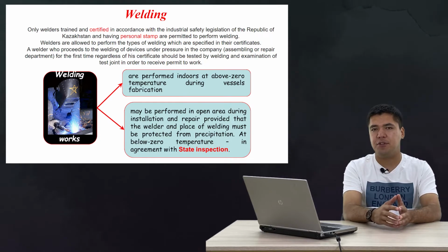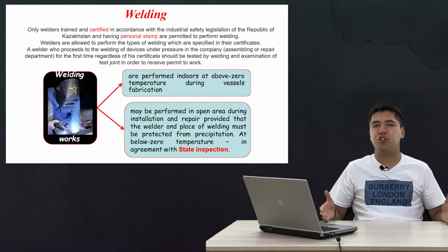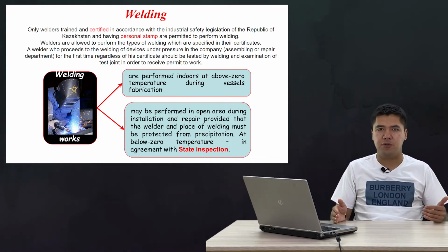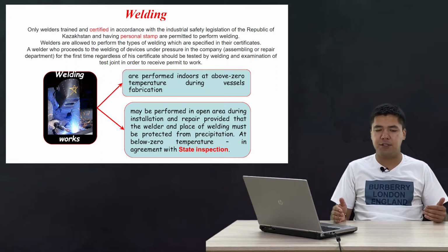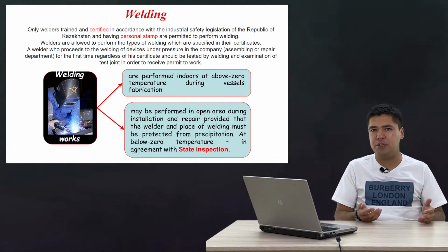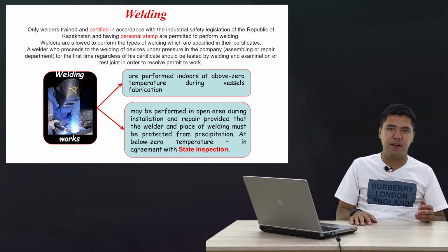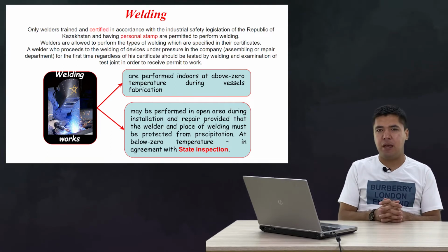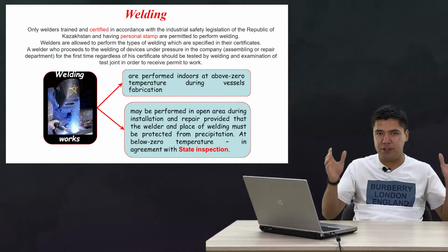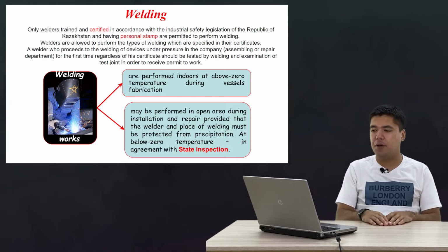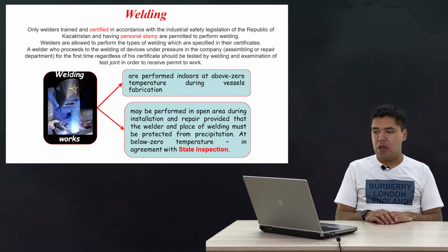Anyway, the welding place shall be covered with shelters made of different materials, in order to protect the welding point from precipitation like wind, snow, and rain, also from dust. The welder with the welding part shall be covered with this shelter. It's a requirement of the national standard.